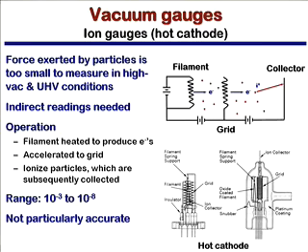But the thing about them is that they have a good range. They're pretty robust. They operate in medium vacuum down to pretty high vacuum. They're not particularly accurate, but in the end, you don't care, right? Because your goal is to make sure that your vacuum system's working. And so you turn the thing on, you use the Pirani gauge, it gets better down to 10 to the minus 4. Your other things kick in, your better vacuum pumps. It continues to pump down to, okay, bottom of the range, and you're happy, okay? You don't care so much if it's 1 times 10 to the minus 8 or 5 times 10 to the minus 7. You just know that that's what you're going to get out of your system. So they work pretty well.